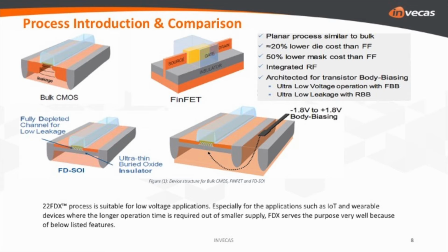So when it comes to performance, if we keep the planar bulk transistor as a reference, 22FDX certainly gives a high performance, as good as the FinFET. When it comes to leakage, the planar bulk devices have high leakage. 22FDX has lesser leakage, whereas the FinFET technology offers the lowest leakage.